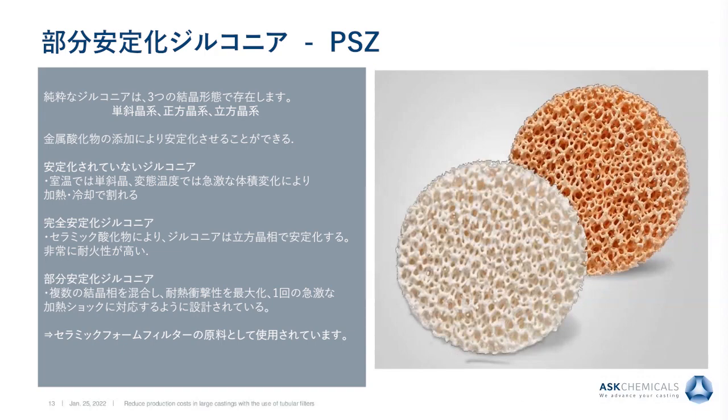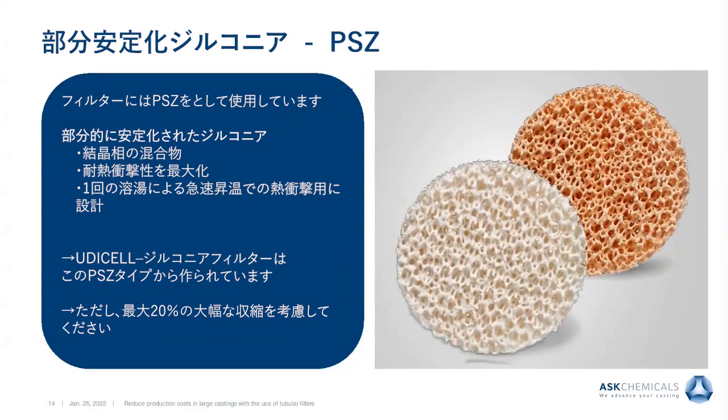As mentioned, the best ceramic material used for filtering high temperature steel and iron-based alloys is partially stabilized zirconia, utilizing magnesium oxide as a stabilizing agent. This material exhibits excellent thermal shock resistance, as described already by me, and furthermore, it has very good chemical, mechanical, and thermal ruggedness.